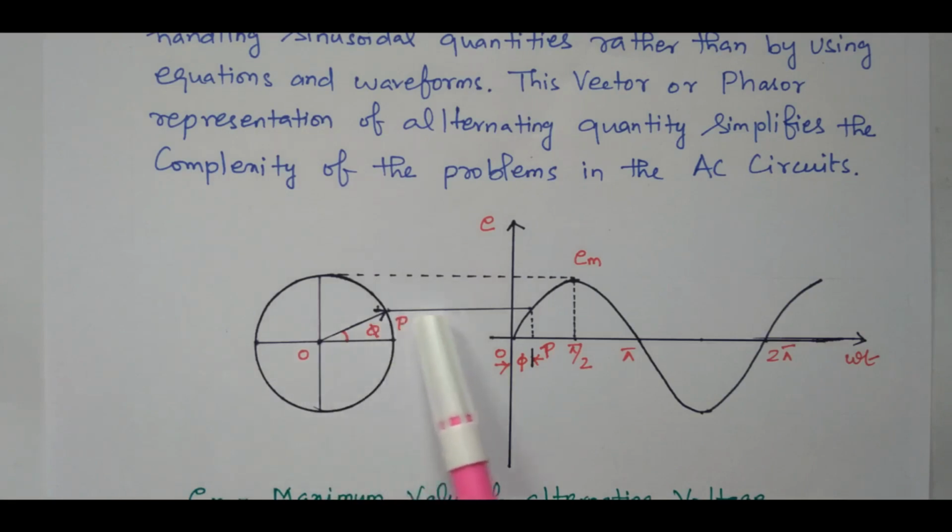So here we have the point 0 to P. This equivalent line is drawn that intersects at this point. So this is the point P. This angle is phi, this angle is also phi, both are equal, right? When the voltage increases, the angle also increases. This angle can be easily measured from the Phasor diagram itself, right?